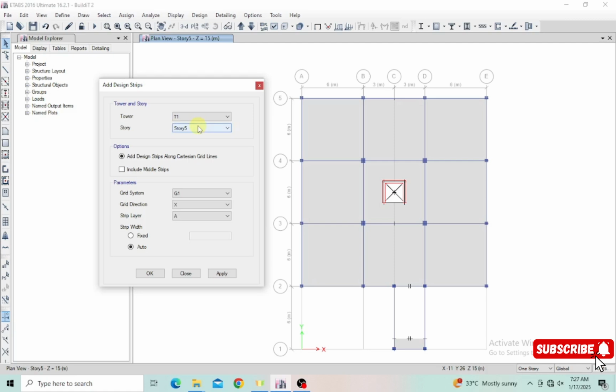So story 5, add strip along Cartesian grid lines. You are going to check this, and we are also going to include middle strips, so you are going to check this box. So this is one of the important parts. So the grid system, that's G1, and the grid direction. When it comes to this, we have to specify the direction X, and we are going to give it a strip layer. So we have X and Y over here, and we have A and B over here, and also others. So with grid direction, in the X direction, we are going to assign the A, and in the Y direction, we are going to assign B.